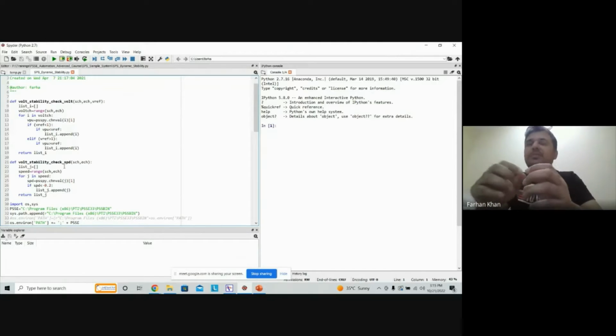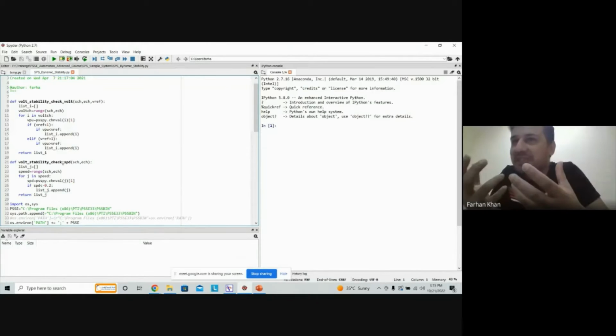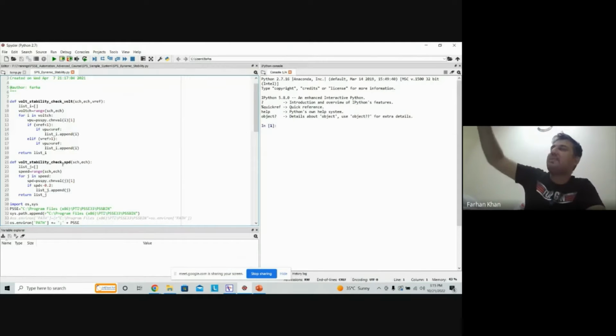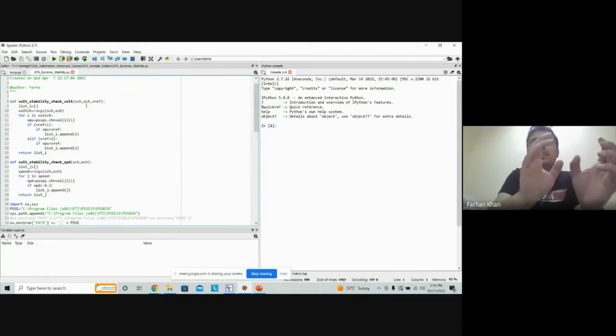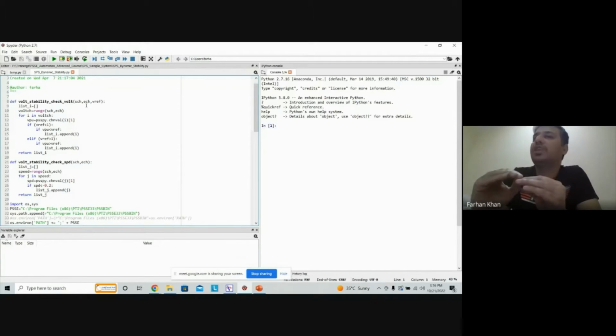For the speed check, speed is basically motor stalling. Remember we discussed that in Texas or California, where you have a huge amount of motor load in your system, you can expect that following this fault-induced delayed voltage recovery, some of the motors might stall. They may not return back to their original position due to this decrease in voltage. They may reach their maximum torque, so they may go into stall position. This is exactly what I'm checking here. This is my SCH, ECH: my starting channel, my ending channel, and V reference is the reference against which I want to check my voltage.